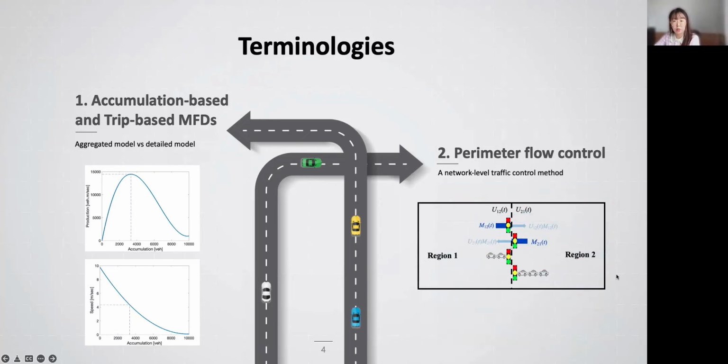In this paper, we use a simplified network and use U12 and U21 to denote the perimeter controllers. Actually, the perimeter controller is implemented through coordinated traffic signals installed at region boundaries to regulate the rate of transferring vehicles from one region to another to prevent hypercongestion.